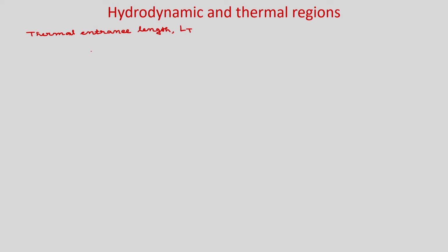So, now u we consider as u average. So, for this case, delta T by x, if you consider u is order of u average, then it will be 1 by root Rex into Prandtl number, right.